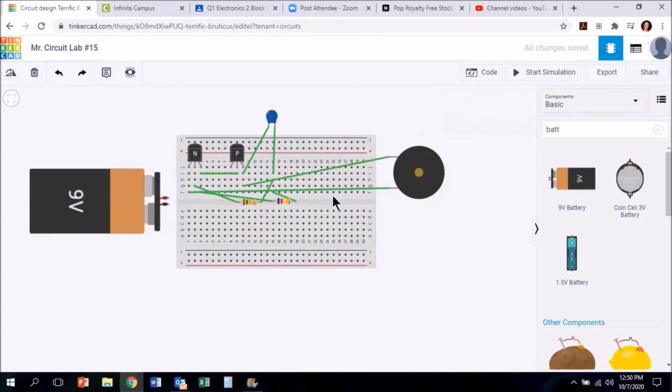Okay. Lastly, we can bring in our 9-volt battery so we can test our circuit. So I'm going to bring in the positive, or the red lead first, and that's going to go in line with lead number 1 of Q2, and that's going to go in row G. I'm going to change that to red. And now the black or negative battery lead can go in row I in line with our first lead of Q1 here. Change that to black.